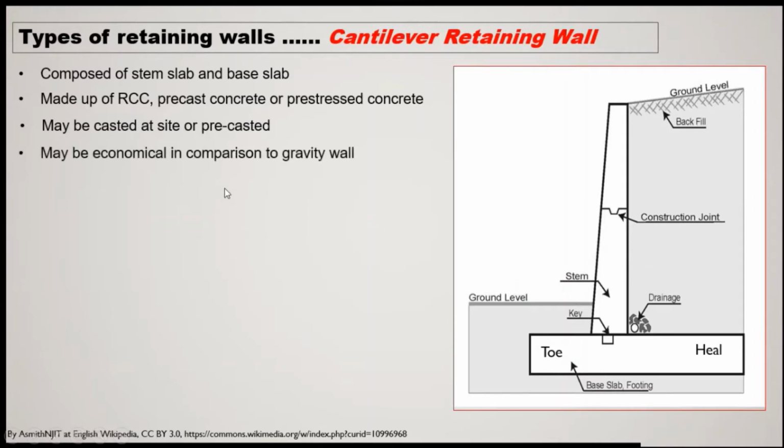It may be economical in comparison to a gravity wall. You may be aware that in a gravity wall, all the stresses will be taken care of by the weight of the gravity wall. So that's why the size of the gravity wall is larger as compared to the cantilever retaining wall.